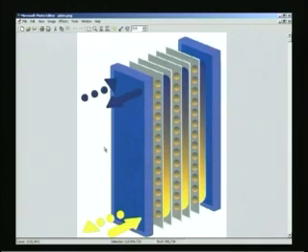Now, in the parallel plate heat exchanger, these are the plates which I am showing here with the cursor: 1, 2, 3, 4, 5. These are the end plates which are helping to clamp all those thin metal rectangular plates together. So, we have a series of passages in the form of parallel plate channels, like this is number 1, number 2, number 3, number 4, number 5, number 6, 6 parallel plate channels.